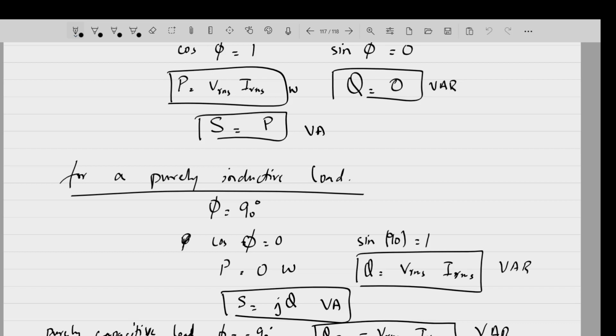Reactive power जो है, it is not the power that gets consumed in the system. It is only the power that is oscillating in the system, that there is an exchange of some amount of power between the source and your reactive elements because of the nature of inductor and capacitor. They charge in one half of the cycle and they discharge in another half of the cycle.